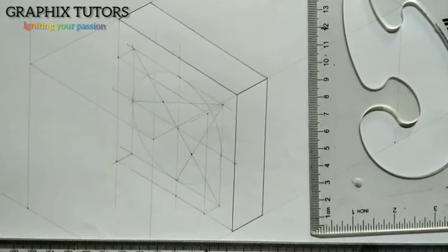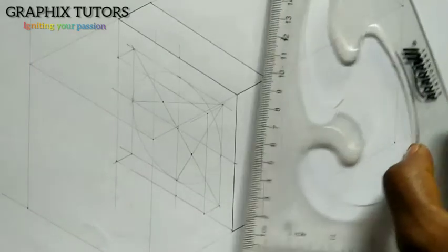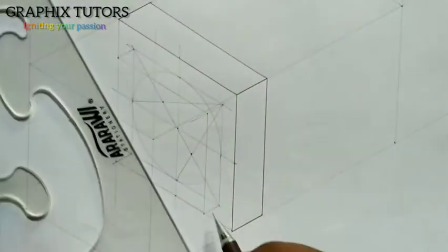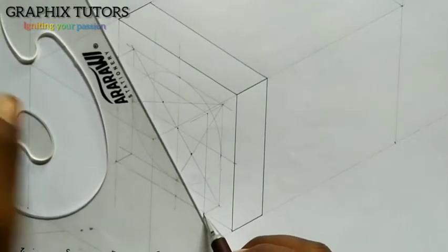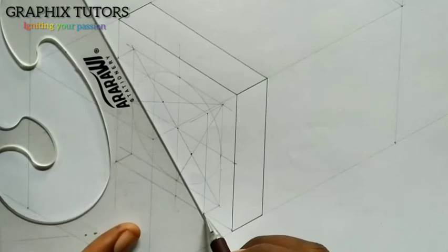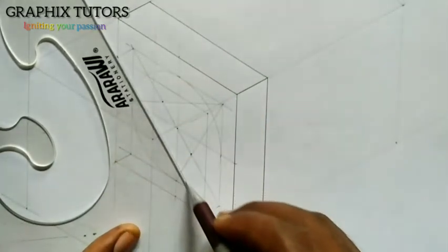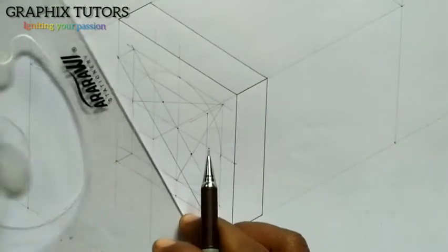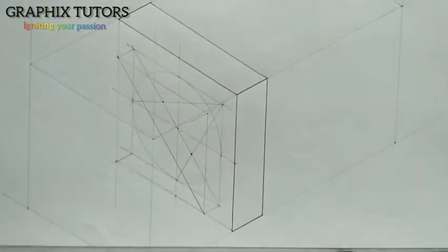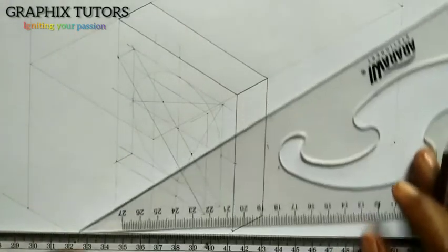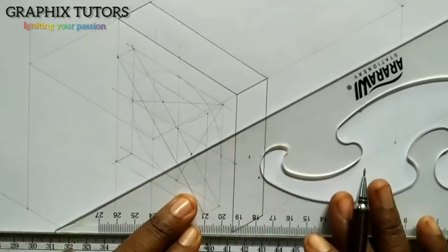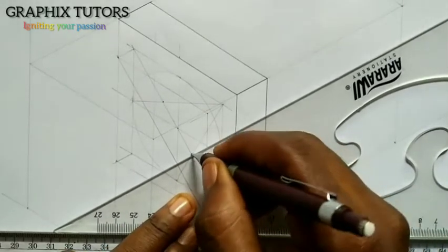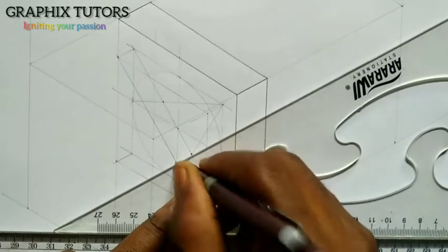So I'll repeat the same process. So it will be more easier for me. What I'll do is I'll join these two points here, the diagonal point here. Join these two lines like this. My front line. So instead of me repeating those same processes, I only transfer the point. So how do I transfer this point? This point, so I move my T-square to that point here. I'll record that from here to here is on the same line.